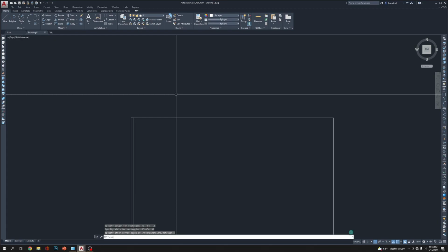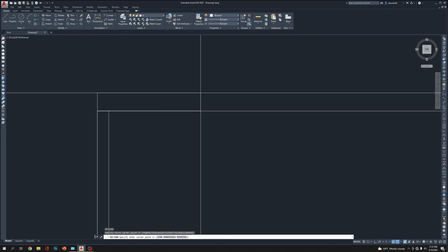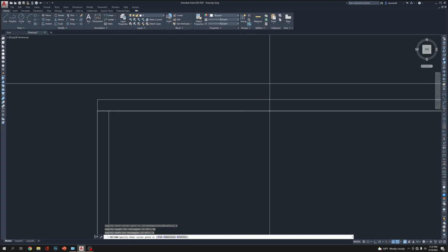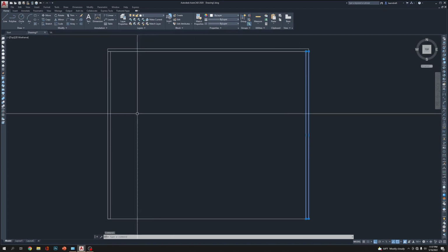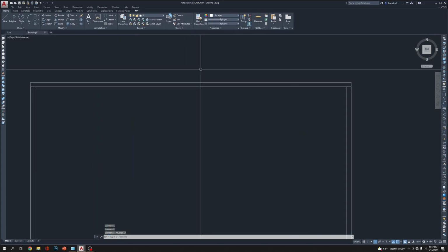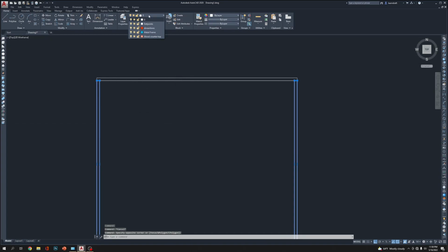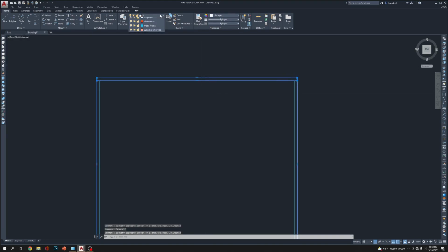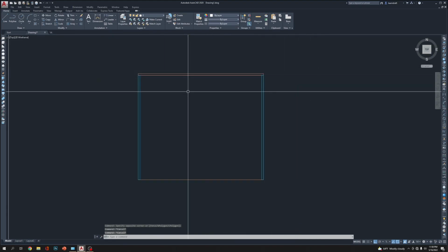and another rectangle going to be from here 36, enter, 0.5. So this is a metal frame, this is a metal frame, and that's the wood. Let me select these two, click here, make it metal frame, escape, select this one, go there, make it wood. So this wood is going to sit on the metal frame, and that's it.